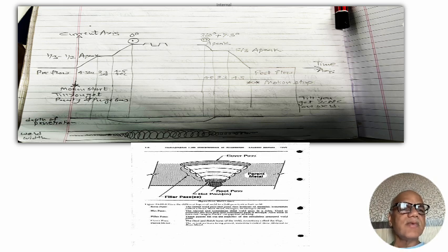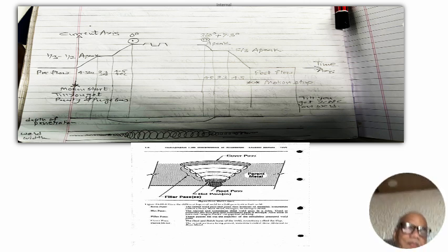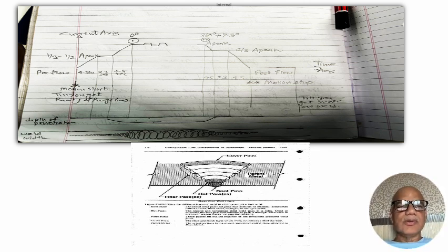So as you see here, we have a pre-flow. After the first trigger, the torch has to be completely flushed, plus the pre-flow is also used not only for flushing the torch but also for creating an atmosphere near where we are going to start the weld, or near the pipe, or inside the pipe if we are going to do purging, or if we have backing strips, how we are going to do that back purging.